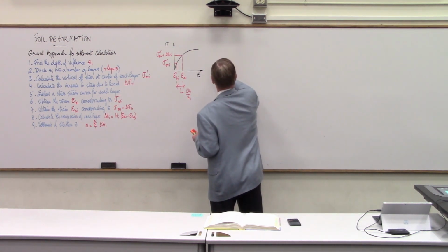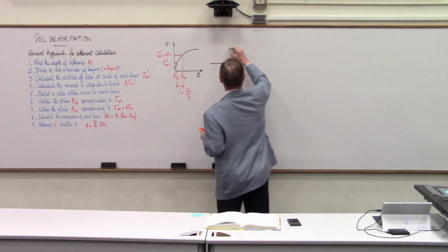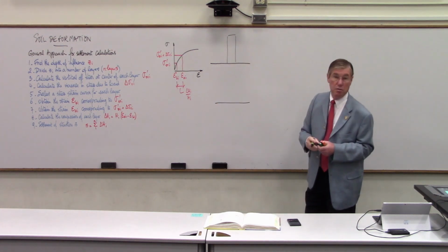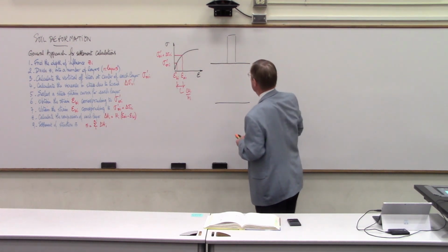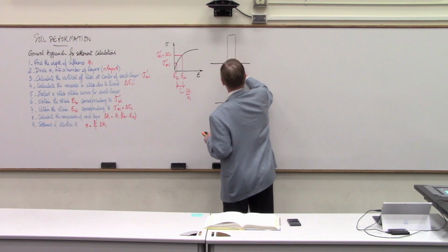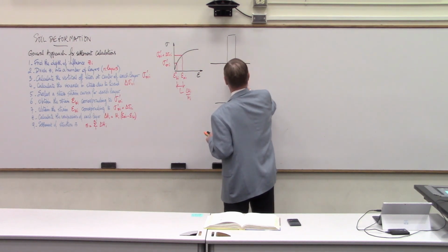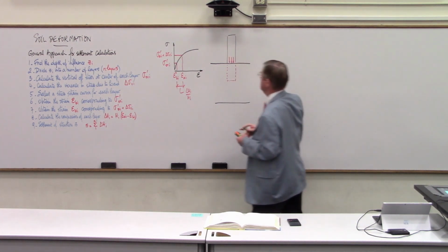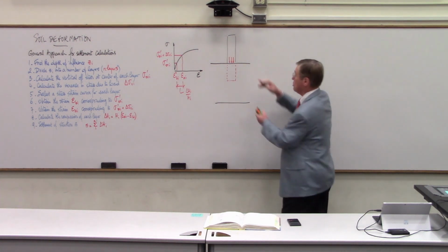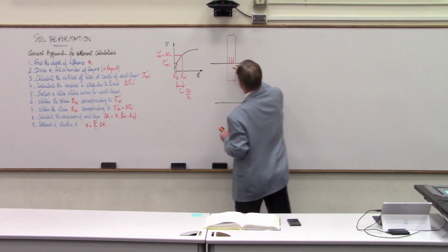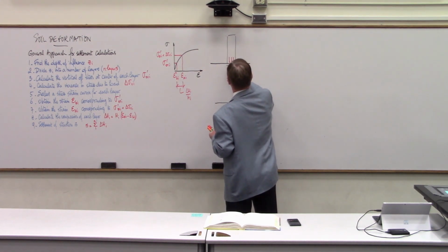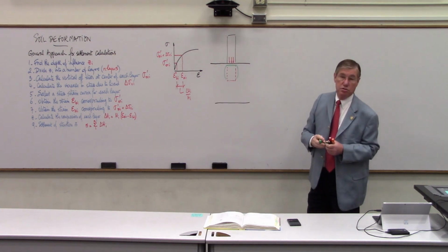The first one is if you have a large building on a relatively uniform compressible soil, then in this case, if you can imagine a certain zone of soil below the building like this, and you're loading that soil zone with this pressure P, you can see that this material is likely to deform by having a certain amount of settlement that takes place under the building, and maybe a bulging on either side of that zone of soil.